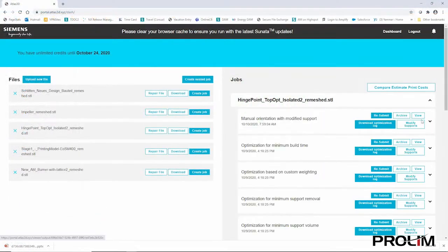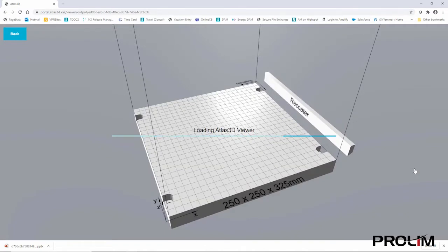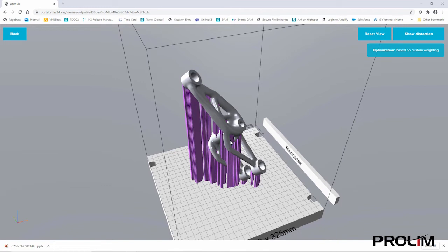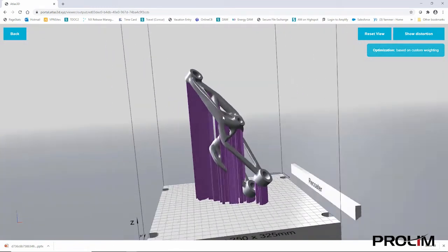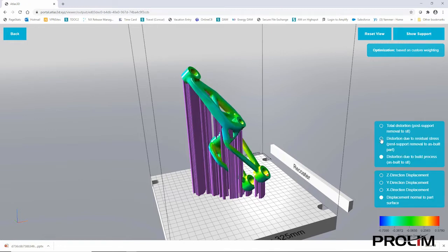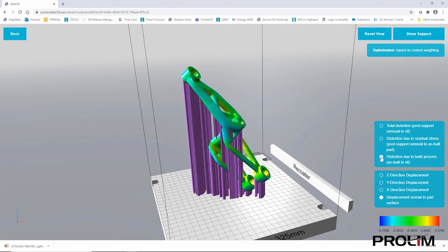Now, once you have the part you want to print, it makes sense to optimize the printing of that part, not as in topology optimization, but as in optimizing the actual production. So for example, Siemens has software for optimizing the orientation of the part in the build tray. This helps minimize distortion, minimize material usage, etc., so that your production is optimal and your part will print with quality the first time.